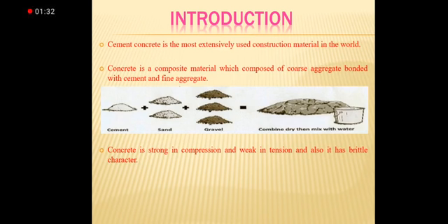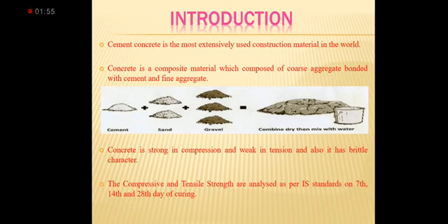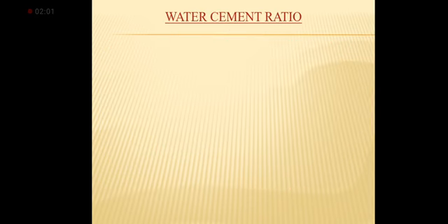But when we go for construction, we try to get reinforced construction, because in construction members both loads, compression and tension, will be acting. To resist the tension load, we have to provide reinforcement bars. So the property of concrete for RCC becomes ductile. The compressive and tensile strength are analyzed as per Indian Standard on the 7th, 14th and 28th day of curing.